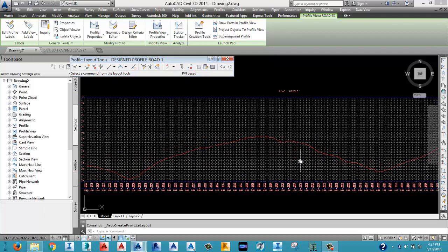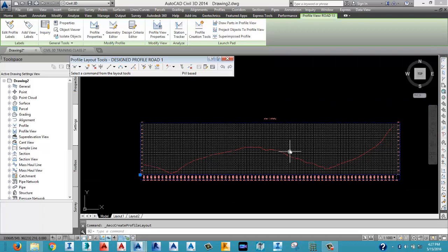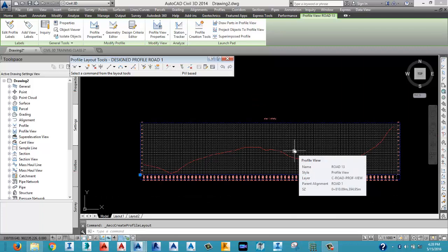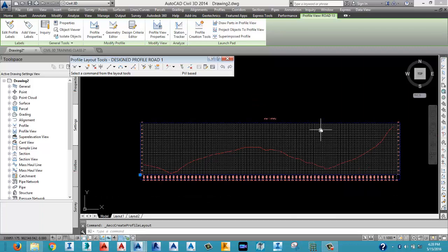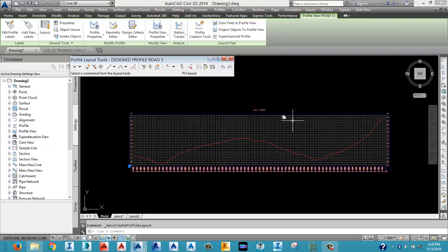Make sure your existing surface profile is well zoomed on your interface for you to actually see the full band. Make sure it's always in your view area so that you can see it very well, because we're about to start the design of this particular road corridor. So I just go to the first one, which is my draw tangent with curves. I click on the drop down. I do my curve settings.